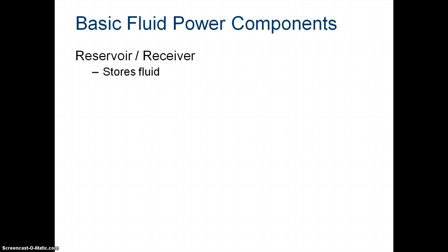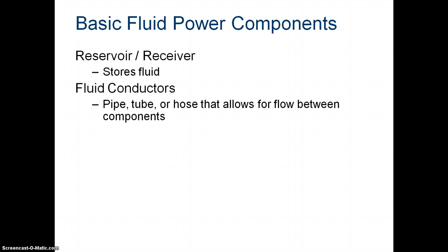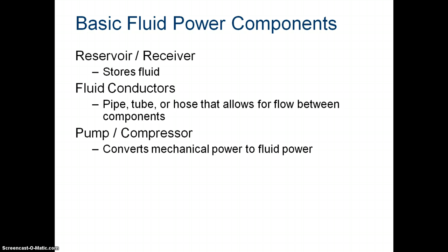The basic fluid components, as I said, are the reservoir, which stores the liquid or the fluid, the conductors, which would be pipe, tubing, or hosing that allows for flow, your compressor or your pump, which converts your mechanical power to fluid power, and your valve, which controls the direction and the amount of flow.